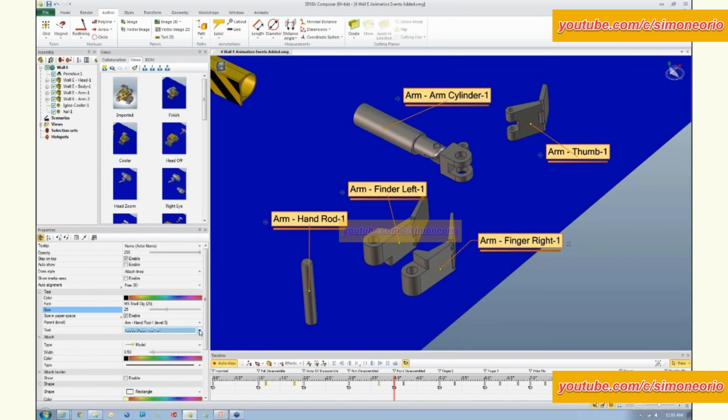Another thing you can do is, what do I want this text to be attached to? In this case, we have it attached to the name of the actor, and that was read in when all the CAD geometry was read in. And then I want to instead have it attached to the component name or the meta property for SOLIDWORKS. That will just change the appearance slightly, but that's how you can attach these things to custom properties that you read over from SOLIDWORKS.